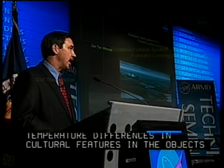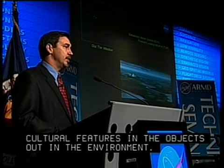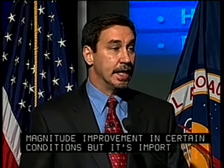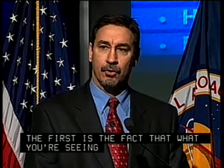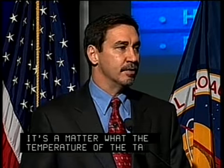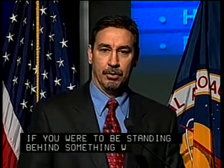FLIR, again, can provide orders of magnitude improvement in certain conditions, but it's important to understand two of its limitations. The first is the fact that what you're seeing, again, is temperature differences. So it's a matter of what the temperature of the target is versus what the temperature of the background is. So if you were to be standing behind something that would happen to be the same temperature you are, you would actually be invisible. You wouldn't be able to see it.